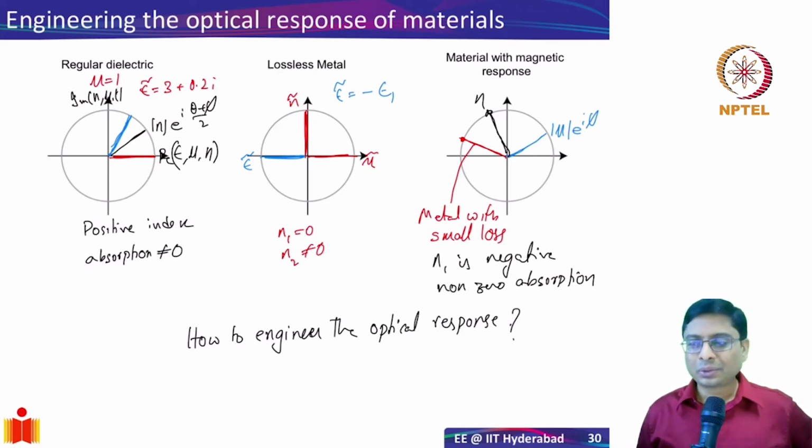If you don't put the phonon absorption into your optical materials, you can never capture that, because all the simulators effectively solve Maxwell's equations in various geometries. Maxwell's equations are always right, but if you do not supply the right material properties in terms of epsilon, real and imaginary parts, and mu, real and imaginary parts, the simulation is not correct.